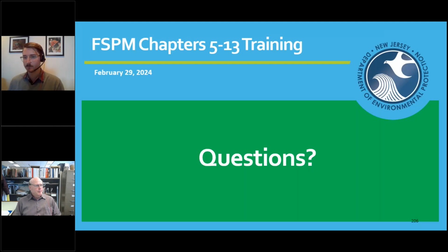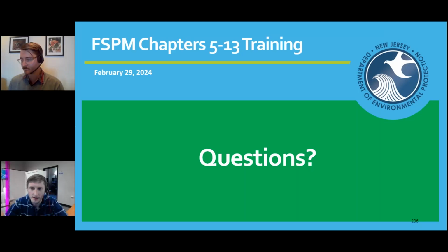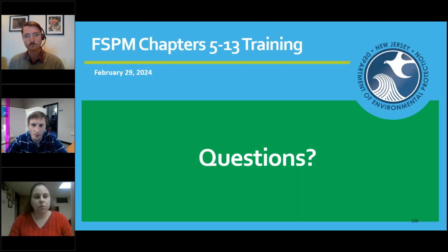Okay, and our next question comes in during the soil gas surveys. On active soil gas grids, can we get elaboration on sample spacing with regard to depth to water? Yeah, so again, it depends on how deep groundwater is. It needs to be driven at least 5 feet above depth to water, and that helps you get a gas signal.